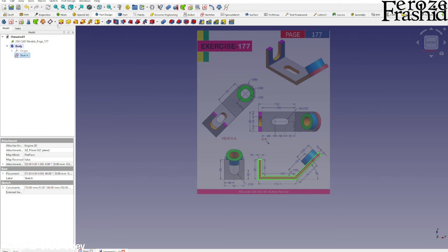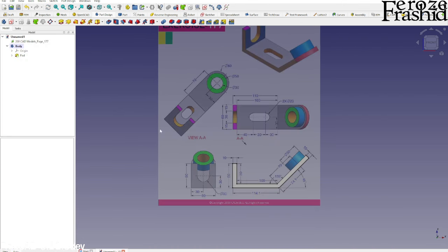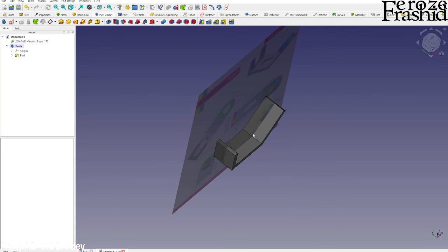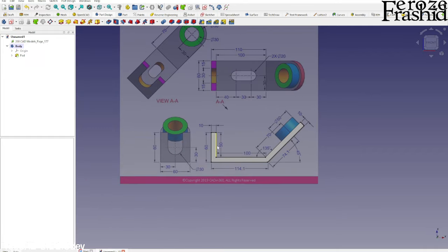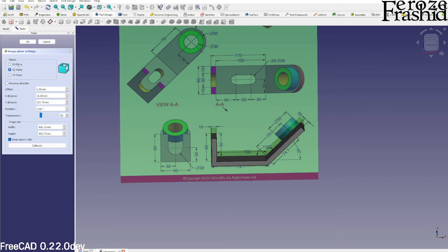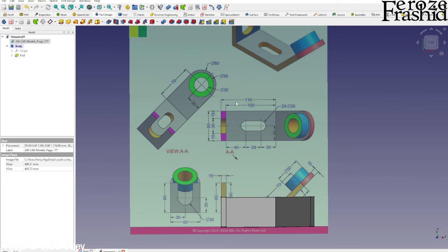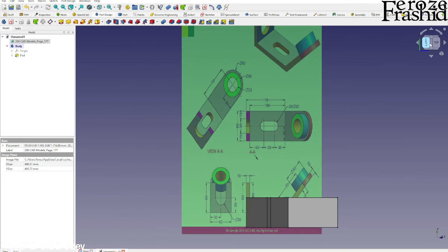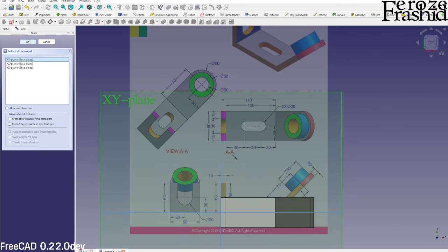As I said, I want to make a pad of length 60 in symmetric to the plane fashion. And there it is. So that is my middle plane, and then the extrusion is on both sides. And now I want to make this hole in the middle, which will be a pocket. I'm going to go ahead and make these two XY plane, and then maybe, actually I don't have to go through that trouble. I can just draw a sketch on the XY plane, right?